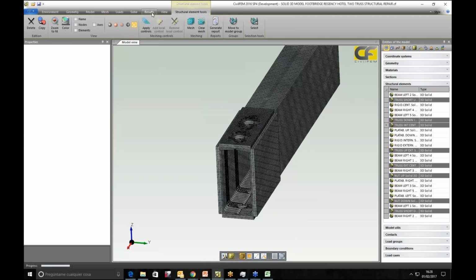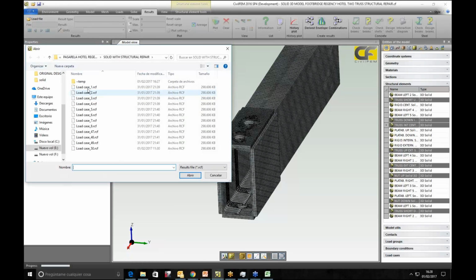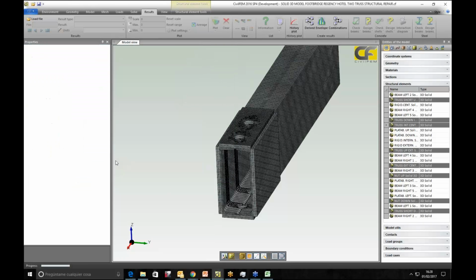So in the results, we can see that we solved the 15 loads, the 15 load steps. It means it could converge and there was no problem, no collapse in this structure. Let's see if there's any damage, just loading the last step. First, we are going to plot vertical displacement, in the set direction.